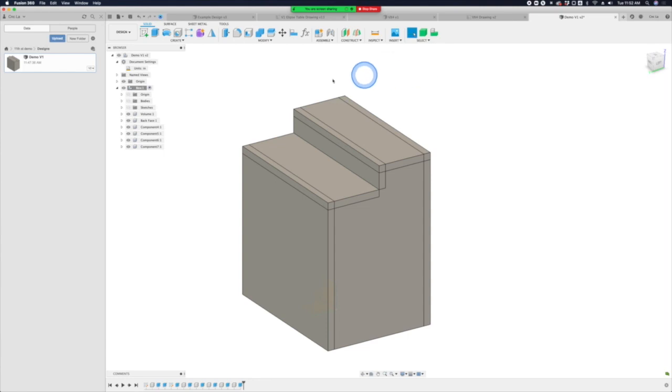This side is going to have all these parts butting over the top of that. This combine tool is how you allow two pieces of geometry to interact with one another. You select your target body first and then the tool body. Your tool body is just any volume that you have created here.